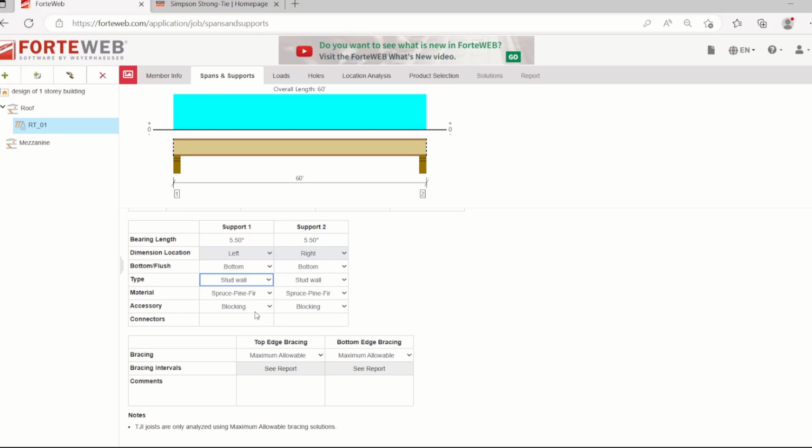And then plate on concrete, right? So for example, plate on steel, if you have a roof beam which is a wide flange section, and at the top of that one you have to provide a nailer, then that's your support, plate on steel. If you have a concrete wall and then you have your sill plate, then you can select the plate on concrete.